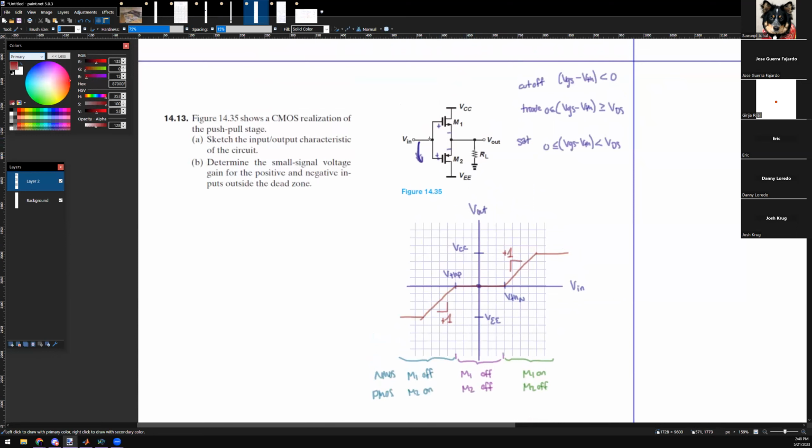What you're saying is correct, but you now have to introduce bias circuitry that puts you here. Vn has to be DC biased to like, I don't know, 1 volt. Do you want to carry a 1 volt battery with you? Does every single speaker you own have a 1 volt battery sitting inside it? No, hopefully not. Typically, you want this plus-minus rail centering. It's also very bad to put a DC bias on your load. Think about this: when the input's not doing anything, the output has what voltage across it? Whatever the DC is. Yes, but suppose in this configuration both are off, what's the current flowing through RL?